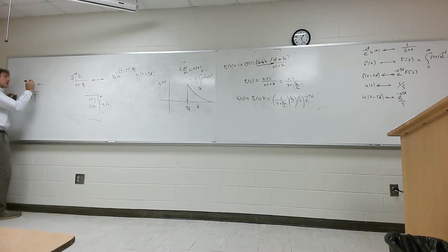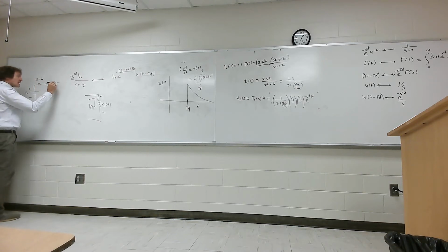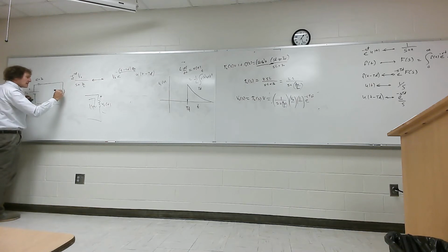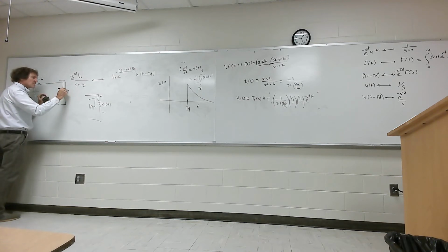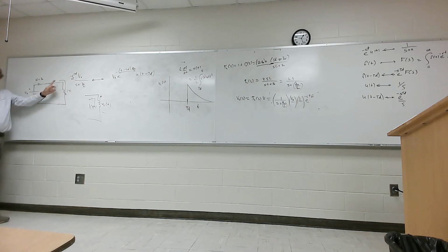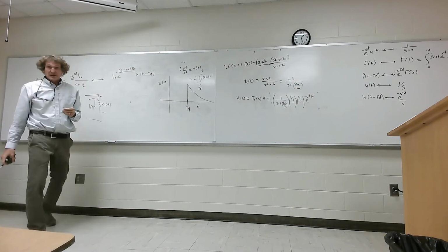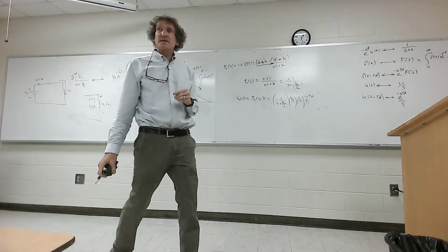Now here's what it's gonna look like as time gets large. This is gonna have a value of Z naught, the switch is closed, and then as time goes to infinity, you can ignore the actual transmission line, correct class? What is this current gonna go to? Just take a look. What does this look like? A short circuit, right? Just V over Z naught. That's what the current will go to on this thing. The current on the other one goes to zero on the capacitor. This capacitor looks like an open circuit. Does this make sense what I showed you today?